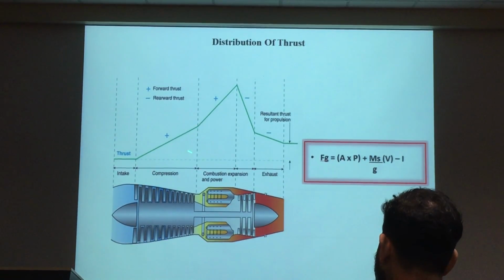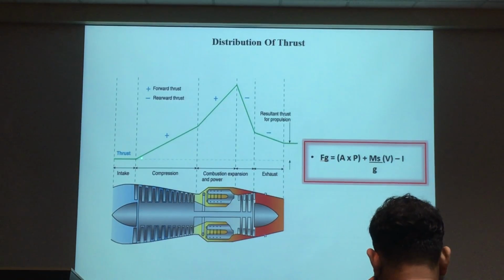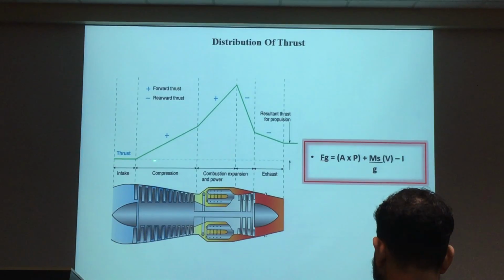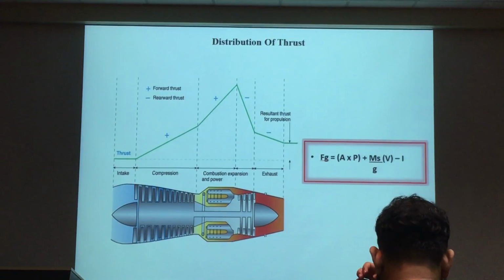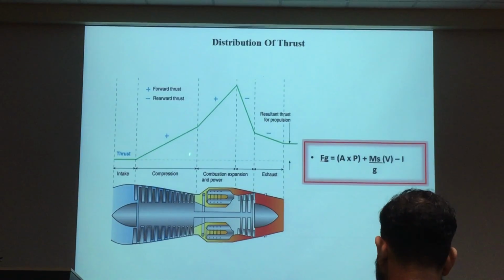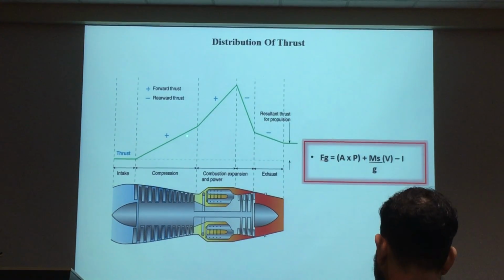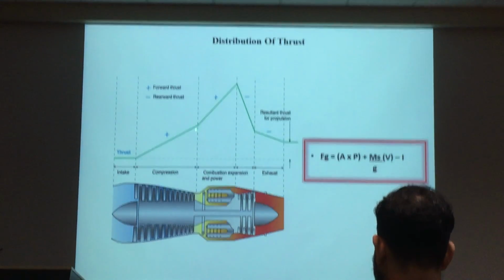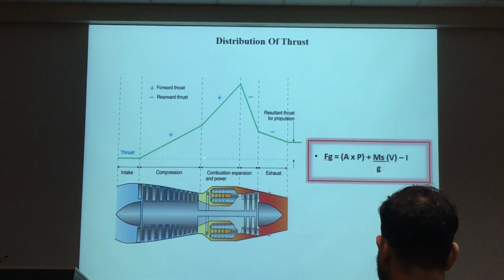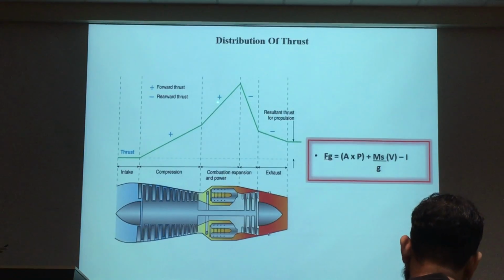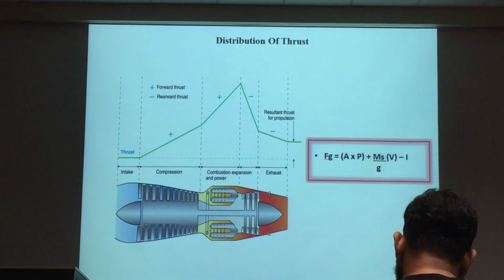If this one is your outlet, this is your inlet. Okay? You treat this inlet, if this line here is actually your atmospheric pressure, you take it as 0. You take them as your reference. So your difference of I at the inlet here is 0. Here is the outlet. Okay? You refer to the next stage, the combustion chamber. Combustion outlet is here, because you use this formula, you're going to have this point here. You minus the I, from here to here. You're going to have a difference here. This is your positive value.